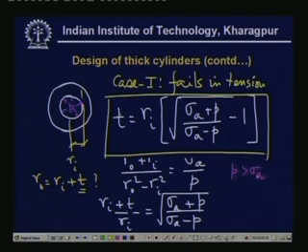So this is very important, that we cannot design any cylinder, using a single cylinder, that will sustain an internal pressure beyond the allowable stress limit. The allowable stress limit is roughly equal to 0.8 of sigma yield strength for ductile material, and for brittle material it is about 1/8 of ultimate stress, that is 0.125 times sigma u, which is the ultimate strength.